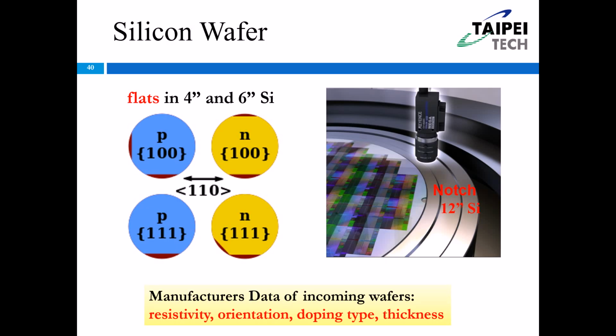And today, I can show you, I also have another one. You see, for this 6-inch silicon wafer, 这是6寸的, you see we only have 1 flat, right? 1 flat on the bottom here. So it shows you it's a P-type 111 wafer, okay? Do you still remember why this silicon wafer is like the yellow or green color? Do you still remember that?